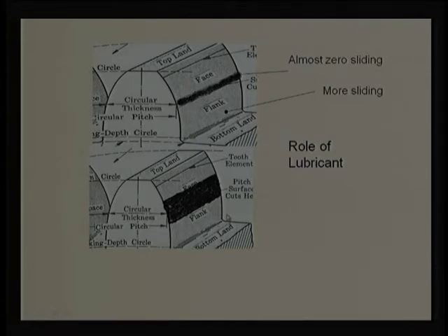In addition, when there is sliding, naturally lubrication is important. Sliding is going to generate higher friction, and to reduce that friction we require lubricant. But the problem is that the liquid lubricant itself gets sheared, so it will give some sort of coefficient of friction. But when I compare solid-to-solid sliding friction with liquid-solid sliding friction, we find a substantial change. That is why we prefer liquid shearing compared to solid shearing, right.